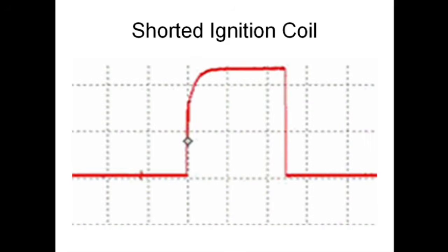Here's definitely straight up vertical, dead giveaway. We have a shorted coil. We have no ramp. This coil is definitely defective.